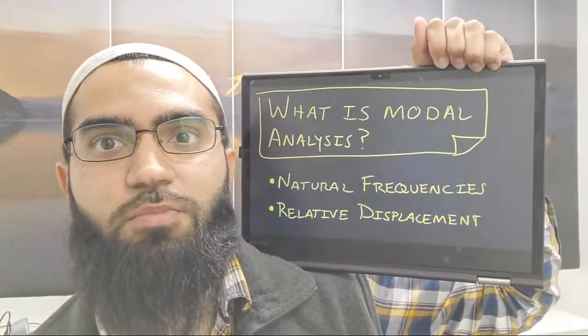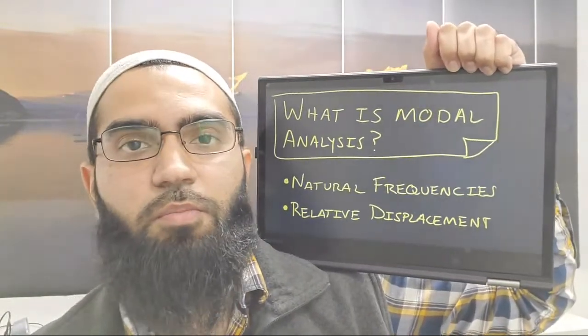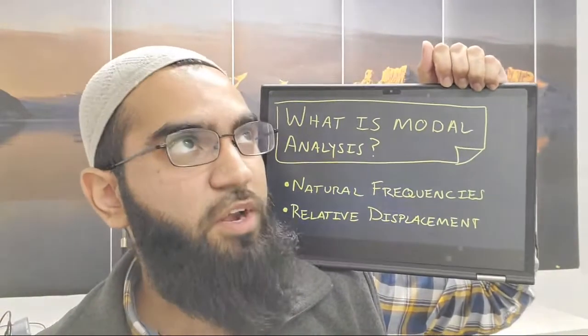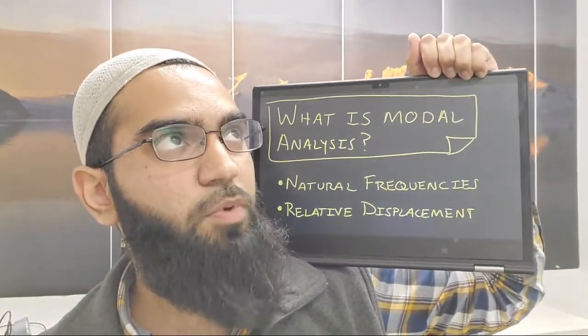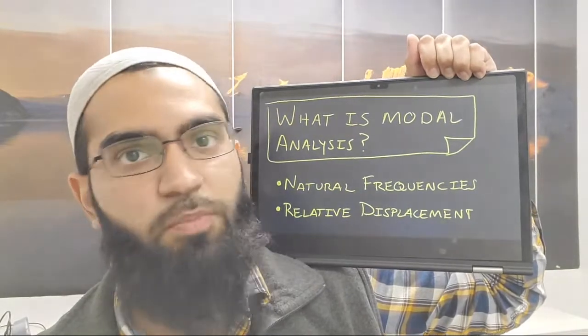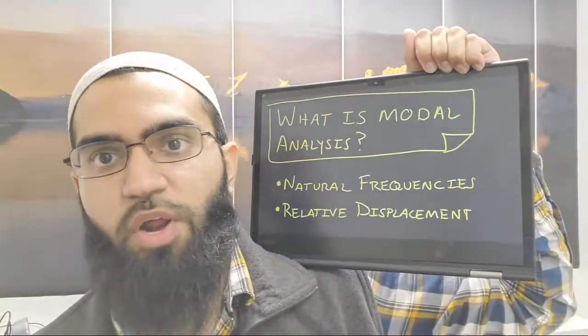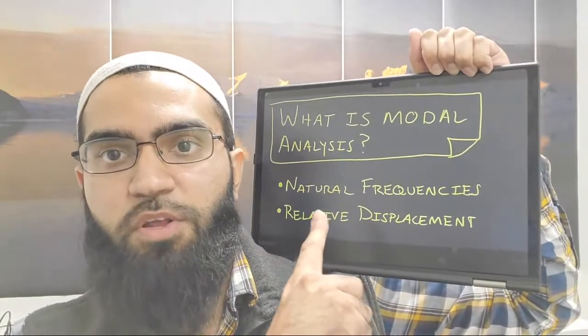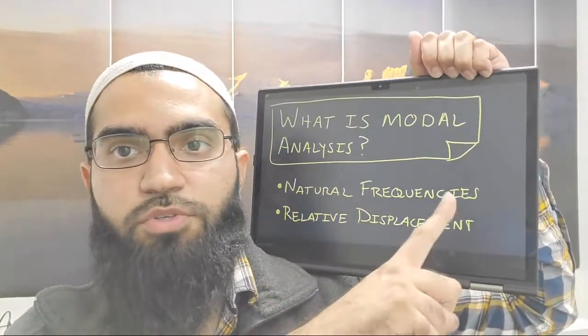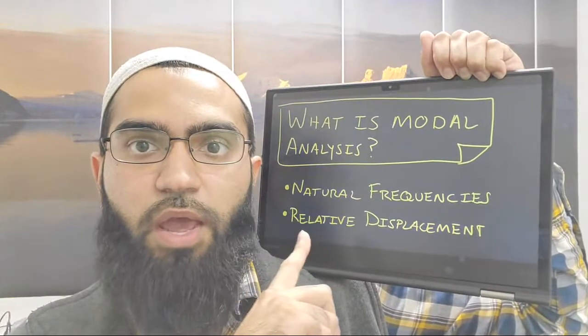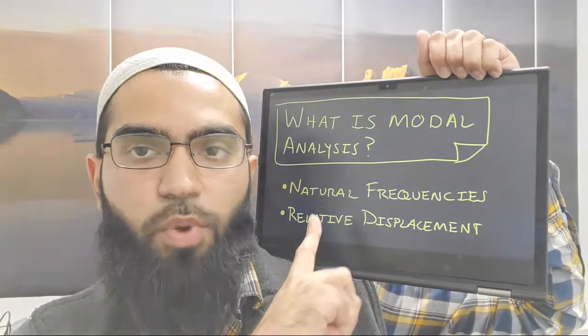So what is modal analysis? In finite element modal analysis, the programs chop up your model into a bunch of little pieces and elements and connect them together, mass springs, whatever. But basically what you get out of it, as many of you know already, is the natural frequencies of your system. And you also get a relative displacement, which is also called a mode shape.